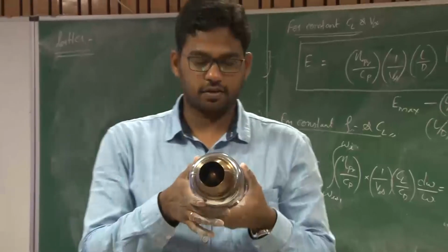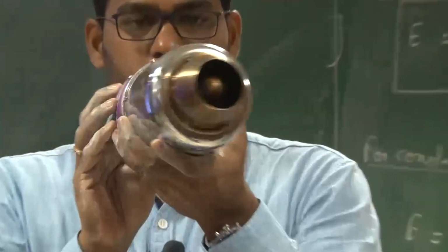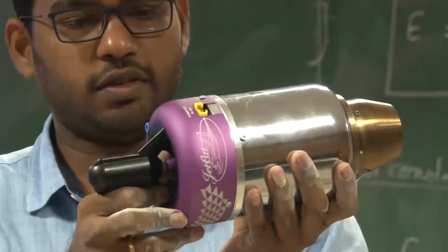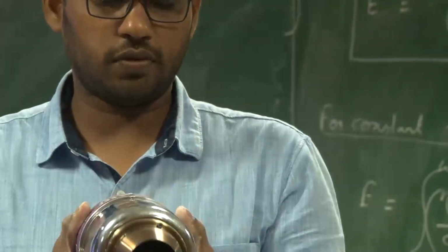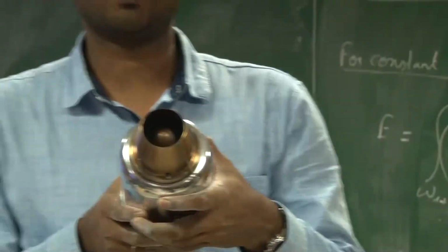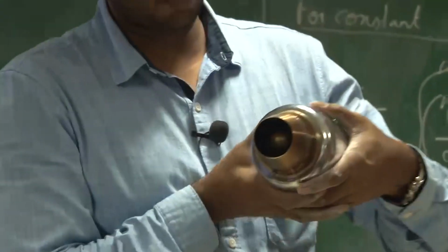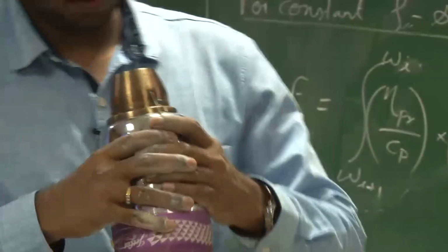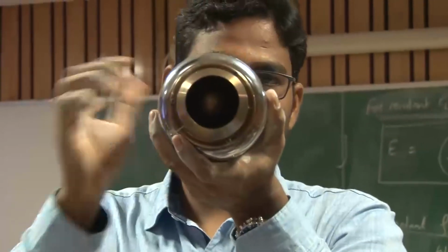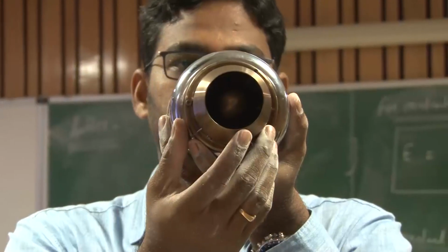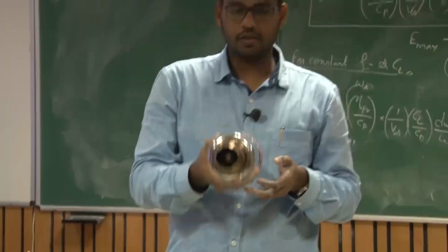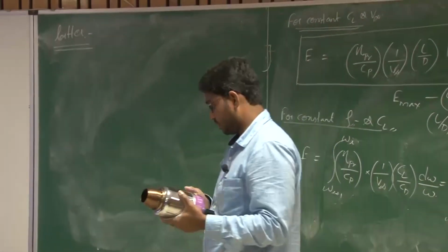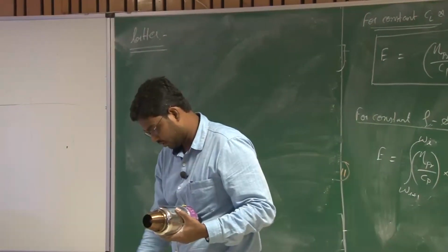There is a JetCat jet engine. You can see this. It's a small, mini jet engine, which can produce 220 newtons force, which is approximately 22 kgs force, right? It can produce a 22 kg thrust. You can see a stator there in the front. It weighs about 1.8 kgs, and I have some of the specifications here.